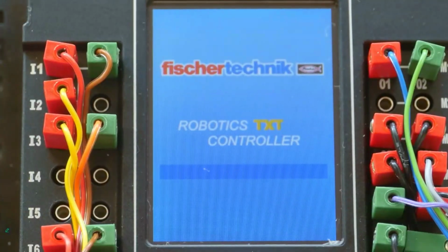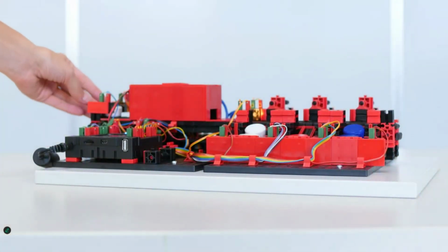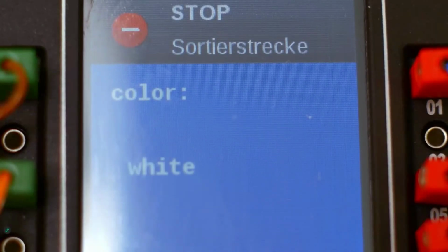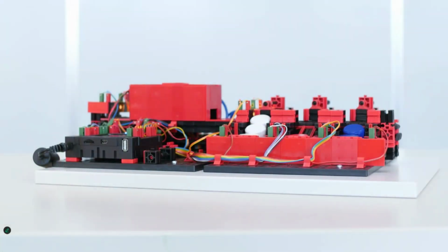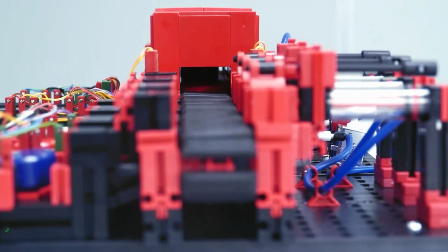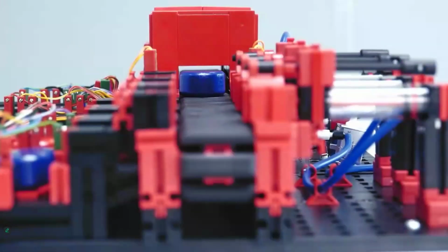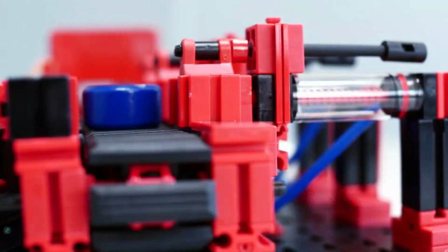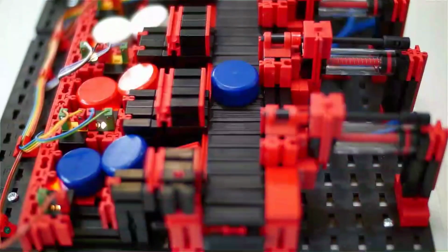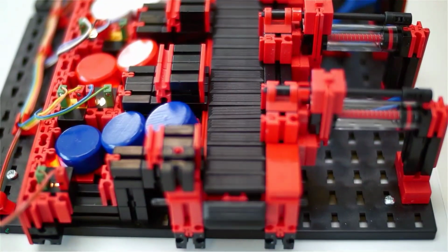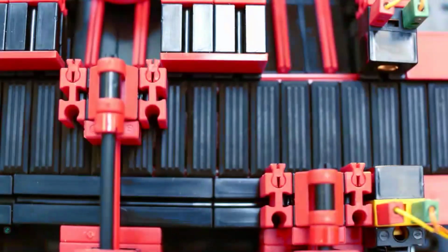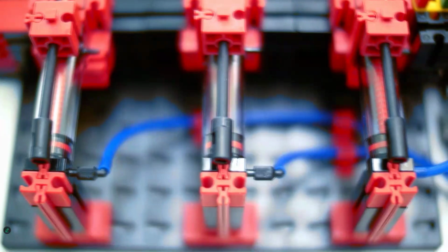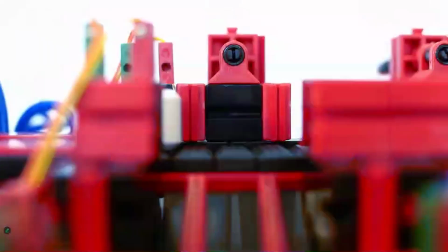The dimensions for the model are approximately 20 by 14 by 12 inches. It has a weight of about 10 pounds. As with the models I've discussed before, the 24-volt version has a relay board for motor polarity reversal and both a multi-pin connector, 34 pins with a grid of 2.54 millimeters, as well as additional PCB terminals with push-in connections for all inputs and outputs. Again, the end user must provide the PLC, the programming, and the wiring, etc. The 9-volt version comes pre-wired to a pre-programmed robotics T controller, and one 120-volt power adapter is required for that.